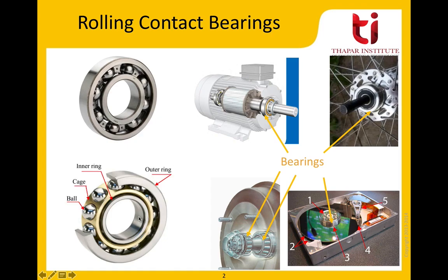So the inner ring is the place where the shaft resides and it is rotating at the shaft rotational speed. These are what you call the rolling elements, and in this case, the balls of the bearing. This golden ring is what you call the cage of the bearing, and its main function is to ensure the precise location of the balls.